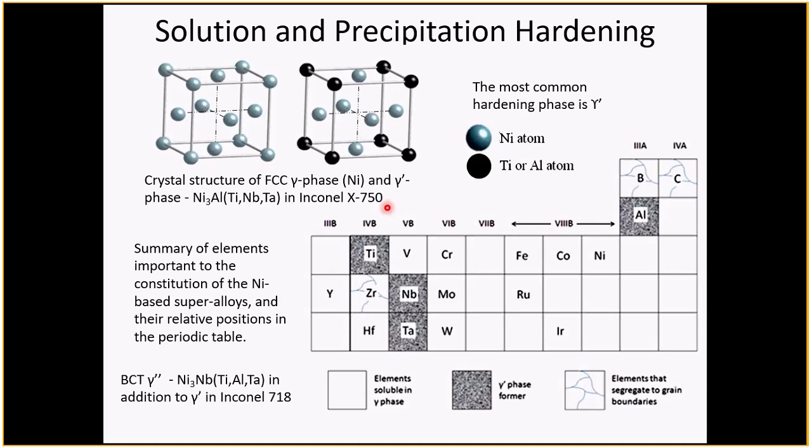Alloys which exhibit what I would consider real superalloy properties, that is, their yield strength increases at high temperatures. These alloys contain a very large volume fraction, 70–80%, of the gamma prime. In Inconel X750, we're talking about 10 or 15% gamma prime.